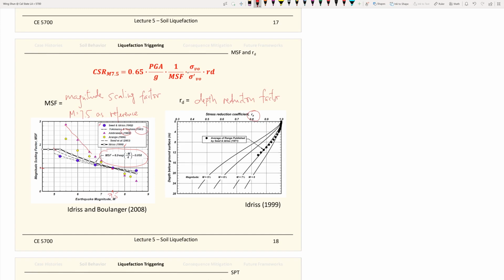When you have a dilative response, you're generating a negative excess pore pressure, which will increase your soil strength rather than decrease it. So you may have cyclic mobility, but your loading and your loading duration may not be strong and long enough to move past the cyclic mobility to the full type of soil liquefaction.